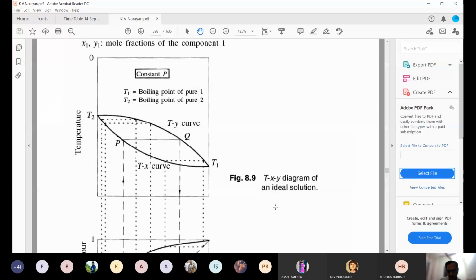It is going to change. 58% is here and 20% is here, so temperature is going to change. And that is why we cannot take that value of P1s and P2s. We have to use alpha, because alpha, he says, is constant in the temperature range involved. So whatever the boiling range between T1 and T2, alpha is normally taken as constant. The ratio of P1s by P2s is almost constant. That is the property we are using now.